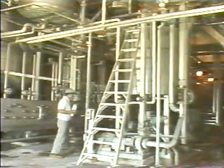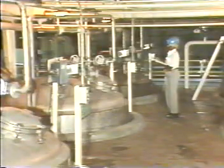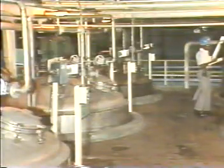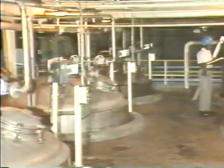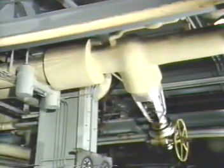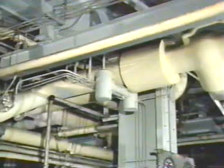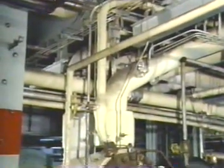One difference is in the way raw materials are fed and handled. In a batch process, exact quantities of raw materials are required for each batch. Because of this, the control system in a batch process must provide a way for volumes of raw materials to be measured. In a continuous process, on the other hand, there's generally a continuous feed of materials, so precise flow control of raw materials is a critical part of the process.